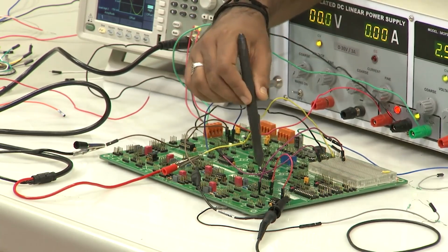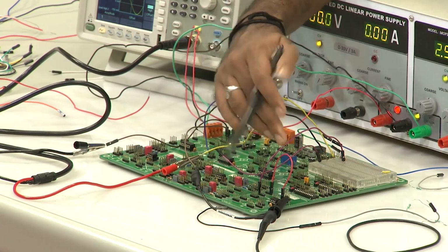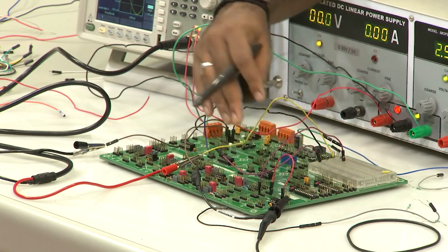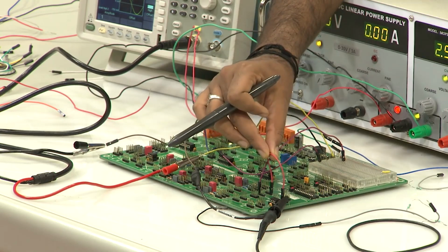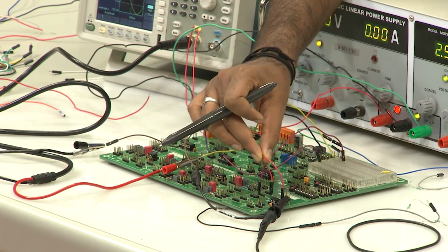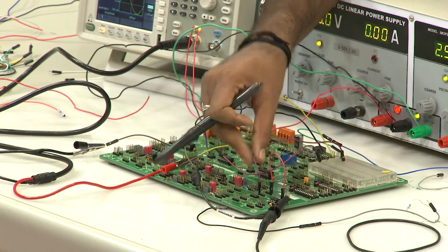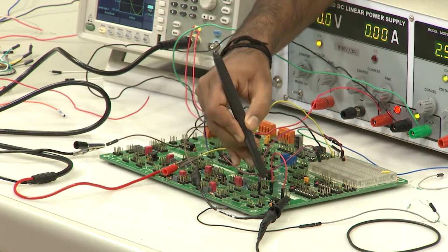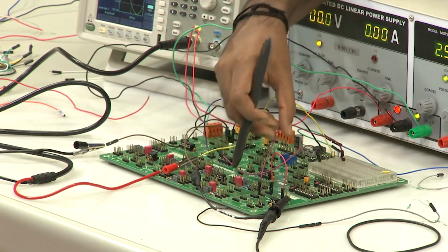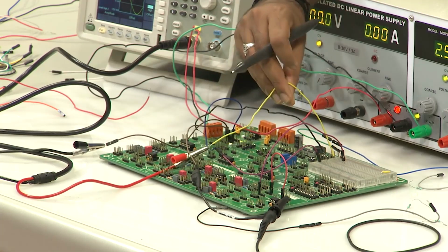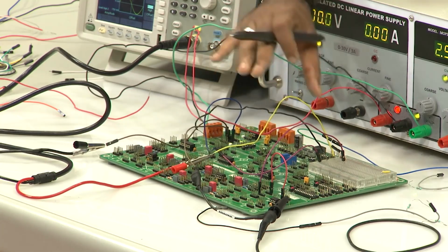So, now let us see what will happen. We have connected a very simple circuit, not much. This red wire connects the output to the negative input terminal. This pink wire connects the input to the non-inverting terminal of the op amp, and the input is given through this yellow wire from the function generator. That is all, that is the circuit.